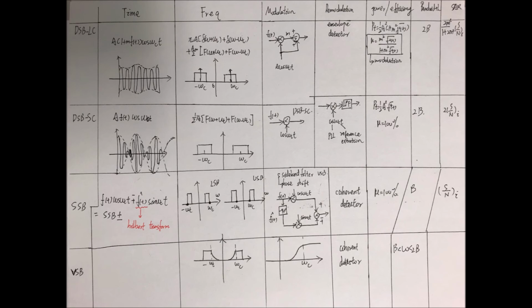This time, the blue one is actually similar to your original signal. However, my envelope, including the blue one and green one, does not look like my original signal at all. Also, when you plot the waveform in time domain, remember every time your signal passes 0, there will be a phase reversal in your carrier.